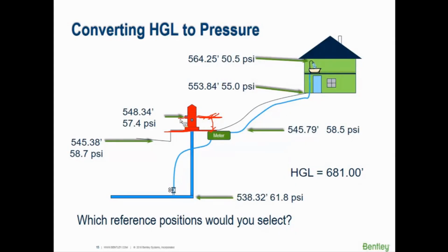That's where you're going to strap on the pressure gauge, right here to the hydrant. Not here by the meter, not here in the ground. You're connecting the pressure gauge right here at the outlet of the hydrant. That's the elevation, ground elevation you would use for that node because it's a sample data point. And now you can really start comparing pressure gauge data in the real world to pressure gauge data in the model. So it's pretty important to pick up on this one too, that wherever you're comparing data points to, make sure that those elevations are the correct ones. Sometimes the pressure gauge may be on a riser pipe somewhere.